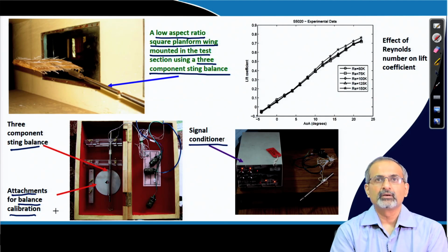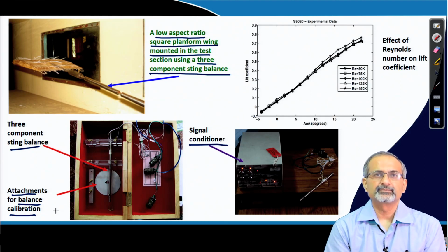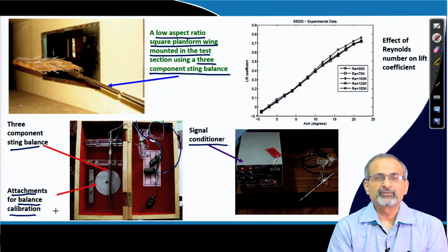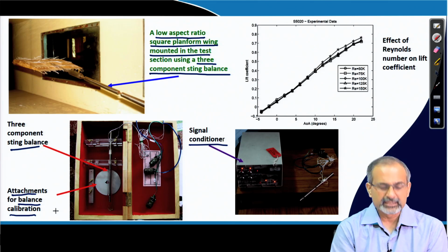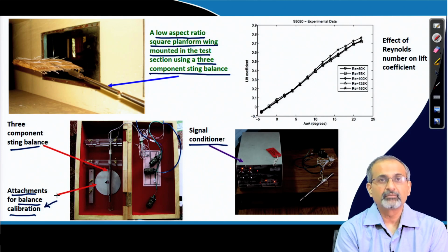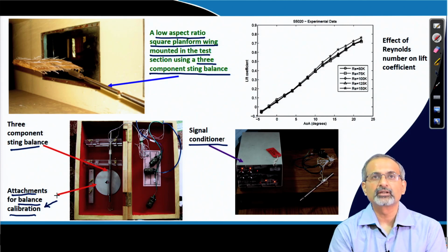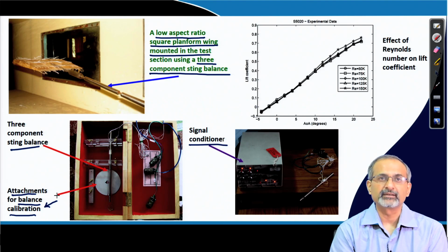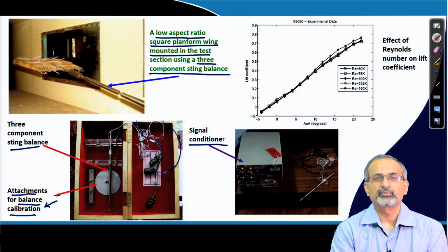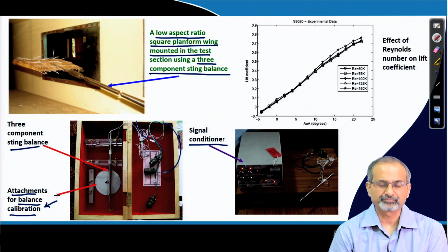So, when you purchase it from a standard manufacturer, you will get an initial calibration report, but please do not rely on that report if it is being used for a long time. It needs to be recalibrated. So, we have discussed this, that the balance has to be loaded appropriately for calibrating each one of the bridges.